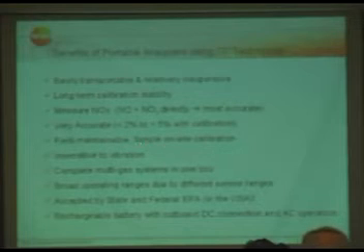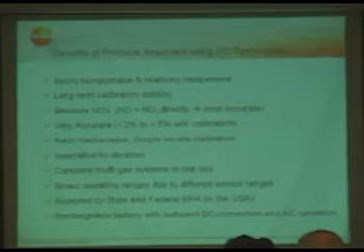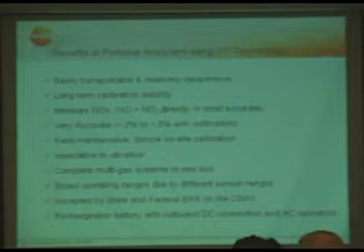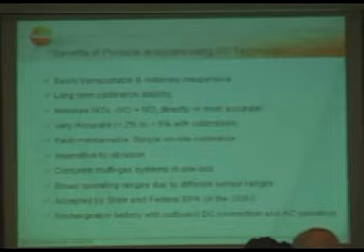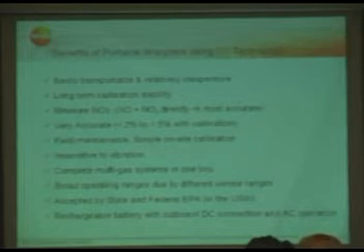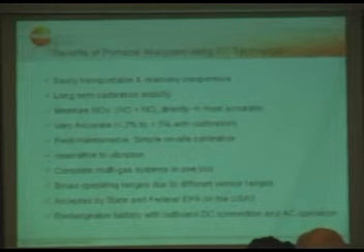That means with a simple on-site calibration and the possibility to change or clean a pump, or with our electrochemical sensors, they are pre-calibrated and have all the calibration data on the circuit board. Every sensor is pre-calibrated, and in case a sensor fails in the field during the measurement and you have a replaceable sensor with you, you can just remove the old sensor which is being used up, put the new sensor inside of the instrument, and then continue the measurement without calibrating the analyzer with calibration gas.